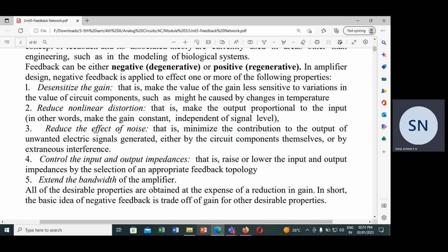This is the amplifier, having the mid-band gain, the high frequency response and the low frequency response. This corresponds to the bandwidth. That means for any change in the frequency, the gain is going to be constant. This is what we expect for any amplifier. Over a wide range of frequency, the gain of the amplifier should not vary too much, so you should get a constant gain.